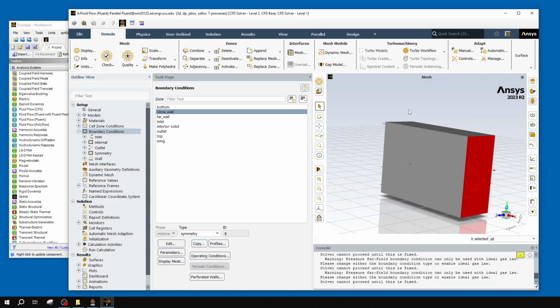And using that symmetry boundary, I can basically halve the size of my simulation while considering an entire domain. So that's very helpful when making your simulation more manageable for your computers. But realize that a symmetry boundary, while pretty good, isn't entirely reflected in real life.